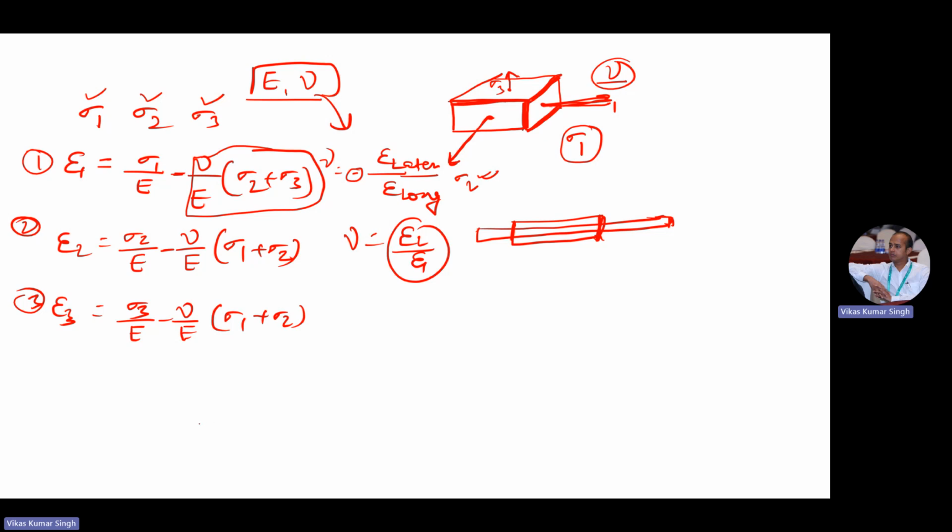Now we are coming back to some kind of energy. Suppose we have a material and this material is deforming. Why is it deforming? Because we are putting some stress, some load, over here, and because of this load the length is increased up to this. So how much work are we doing on this material? P into L. If this is a gradual loading, this will be half P into L. This is the work done which we are doing on the material.